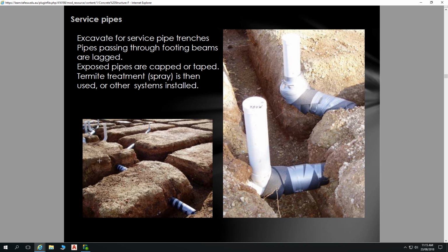That happened to our place, brand new. Someone stuck some old plastic sheeting down the pipe, right, to stop concrete getting in there, I guess. And then it just ended up blocked, so they had to jackhammer the whole laundry up. Expensive mistake. Yeah, and when we're talking about concrete, these very simple things that are not done properly initially, or simple mistakes, can have huge cost impacts.